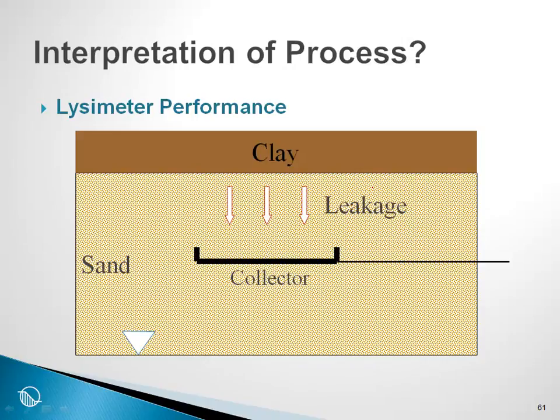As we have already mentioned, in many cases we have facilities where we have a clay liner at the bottom of a reservoir or the bottom of a landfill facility or something. The whole idea is to mitigate and reduce the amount of leakage into the underlying groundwater at depth. And so often we make use of a clay liner. Regulatory agencies then make it mandatory to monitor the performance of the clay liner and to report how successful the clay liner is and how it is performing, as part of the conditions of proceeding with the project.